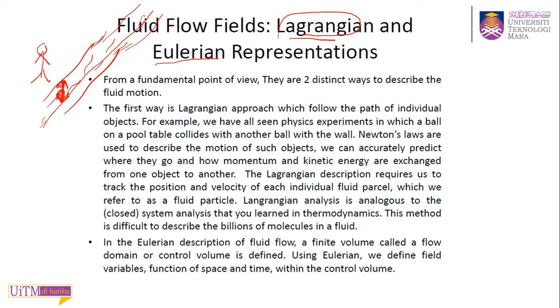So that's the difference between Eulerian and Lagrangian from a bird's eye view. Eulerian will take one finite space or volume and measure it there. Here, he puts it and measures only up to here. Lagrangian will measure the whole river: they will float the probe, whatever he uses, and let it flow all the way to the end, and then he will record and see the velocity of the water flowing in the river.